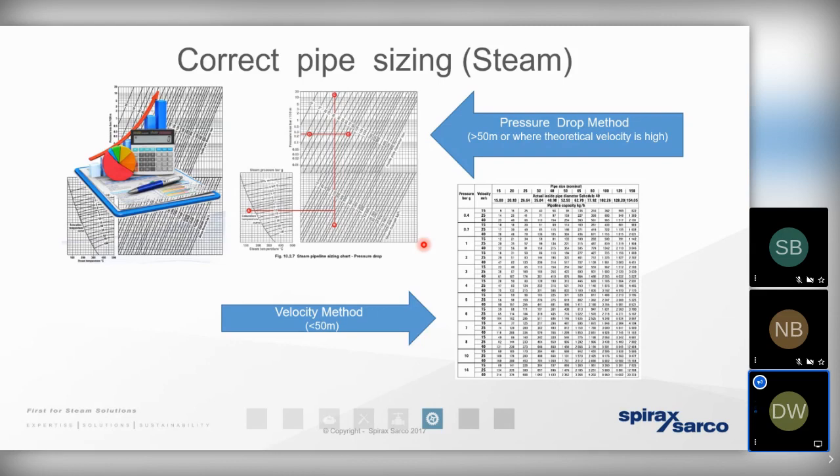don't want to be distributing it at a fast velocity because that's when we're at risk of the various components eroding. And an eroding control valve, for example, well, for one, it's not going to be operating efficiently from an energy perspective. But if it's operating unreliably, then we could have a mass of steam being distributed onto a process when it simply wasn't required. And that could result in product spoilage. So we want to observe the velocity method to ensure that we've sized the steam pipes correctly, and that should be done in accordance with the condition of the steam that it's exposed to.